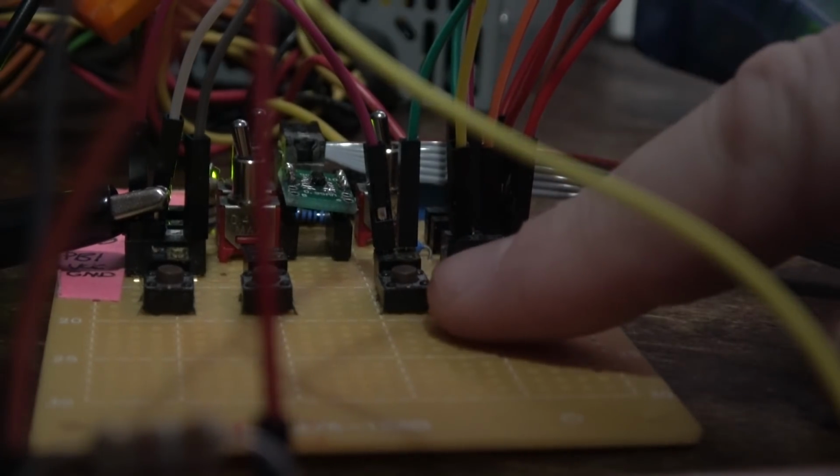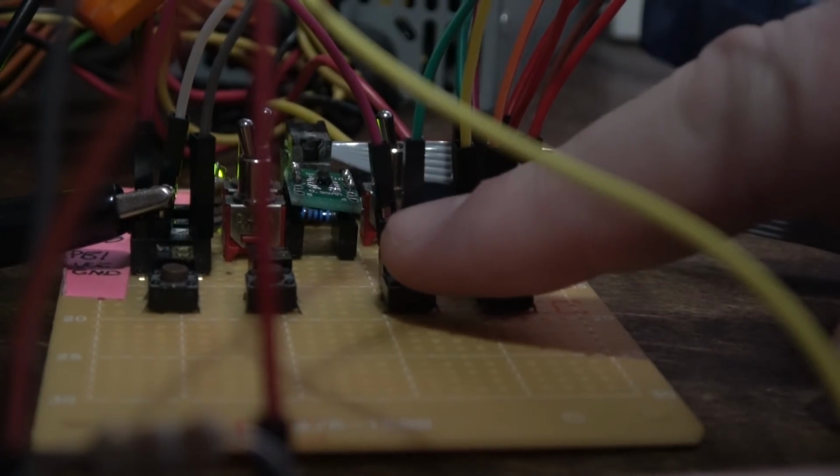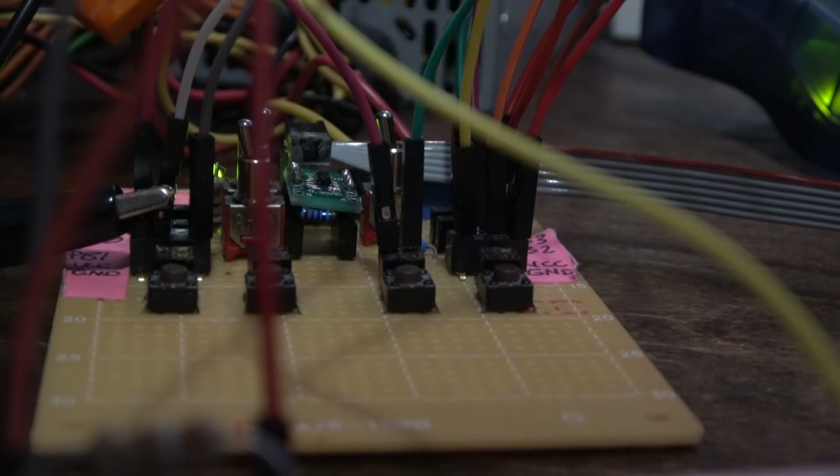I've hooked up this tack switch as our trigger. So basically when I push it, it's going to move the potentiometer all the way to the top range of 5 volts. So if I push it now, it will make our cursor go into the danger zone, a zone of danger. But we'll just use code, and we'll say, okay, if we're all the way at 5 volts, or actually for anything above 1/3 of the range, we'll assume the button's been pushed. Else, we'll update the movement of our character.